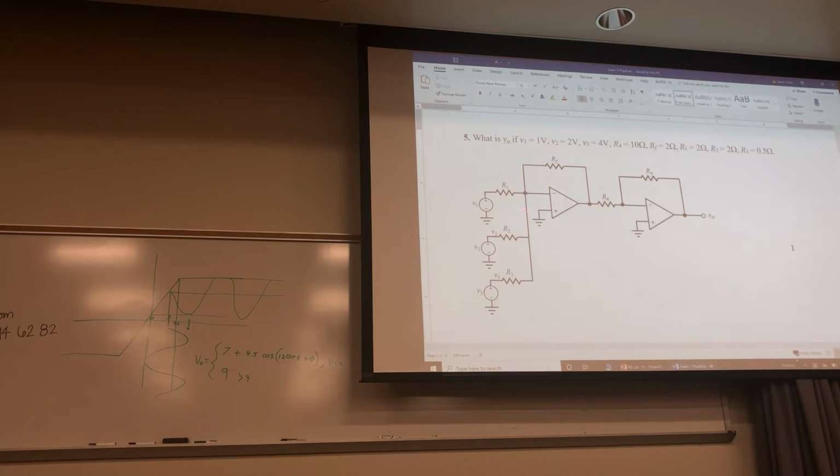So this right here is an inverting amplifier, where the output contribution from each one of these is just the feedback over the input resistance. Contribution from this is feedback over the input. Then you're multiplying that by the input. That's what you're getting here. This right here is just multiplying all that by -1, because these two resistors are the same value.